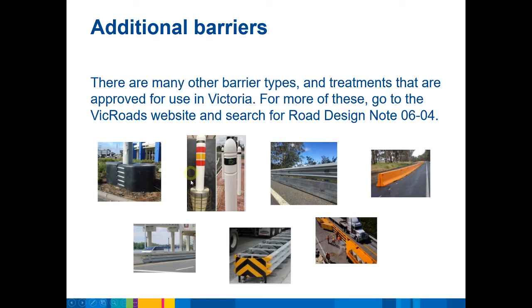We've got crash energy absorbing bollards, which are again quite useful. They've got a special base that's concreted in place, and then when they're struck, they're able to eat up some energy in deforming a small distance. This treatment here is called a raptor or something similar, and it basically clips around a pole where you don't have much space to protect the pole, and if you strike it, it tends to twist, and so it pushes a vehicle away from the pole rather than striking straight into it.